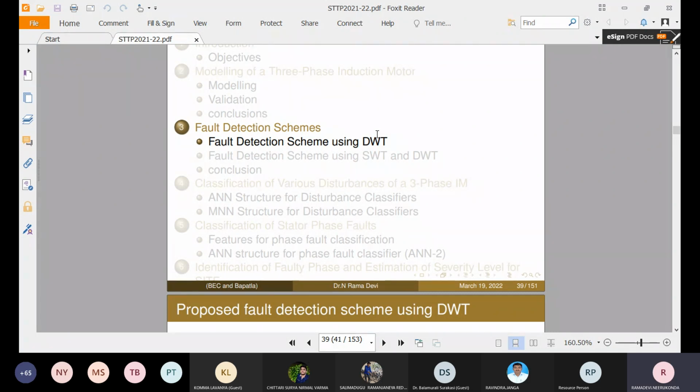Clearly, the FFT analysis of Fourier transform will tell which frequency components exist in that signal. The signal contains a certain frequency component, and that component information is given. But at what instant that frequency component happens in the signal, that information is lost by the Fourier transform and fast Fourier transform. But short time Fourier transform is a window based technique. Because of that, it gives information regarding a short window, so the approximate time instant is also given.